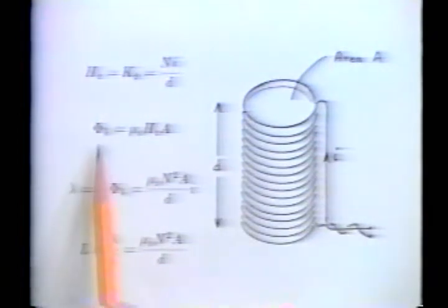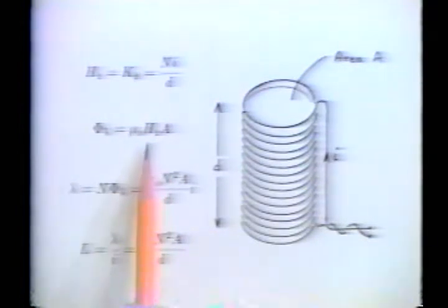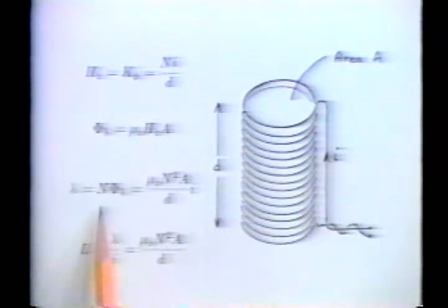We have twisted the terminal ends of this coil to reduce the stray inductance. It is wound on the non-magnetic rod, which has a radius of 5 millimeters. This coil has 50 turns and is 5.05 centimeters long. The coil inductance is predicted to be 4.9 microhenries.